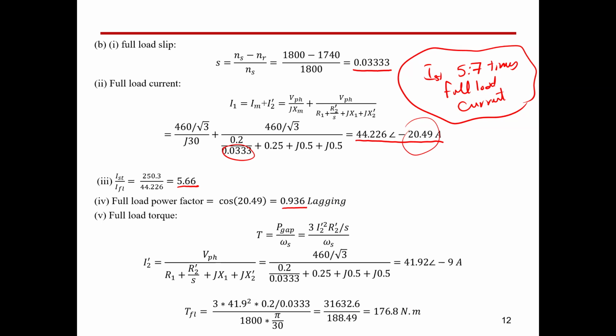So we have class S1, so classes of duty cycle of the machine. Duty cycle means how long the machine can work per day. So we have what's called class S1. Class S1 is continuous working operation, so it works 24/7. So it's designed to evacuate the thermal heat from the motor, from the windings and core, in order to allow the machine to work forever.